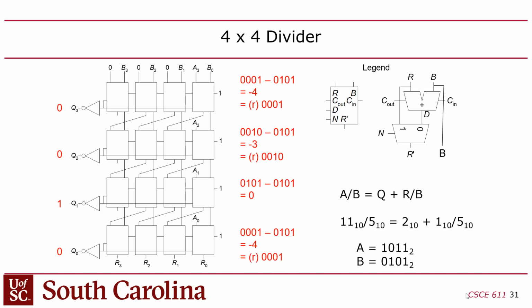So the mux will then restore when that remainder value comes to the second stage, the second row of boxes, it's going to get restored. It's going to get restored, right? Now, does it get restored to 1? Well, no, it actually gets restored to 2, because in addition to restoring the original value of 1, it also does this left shift deal, right?